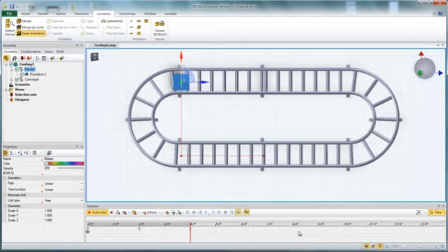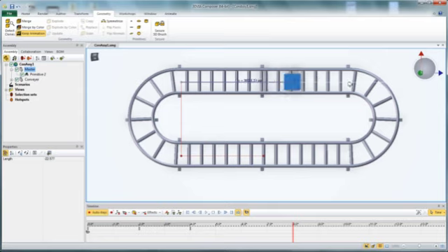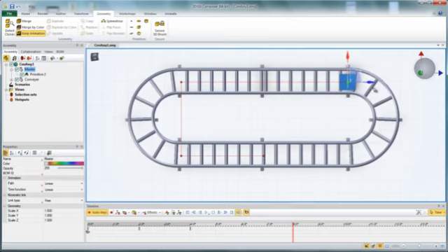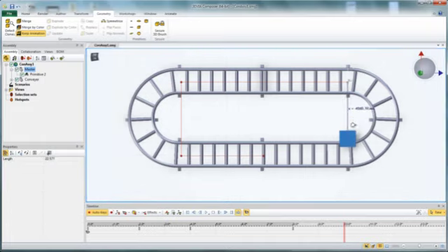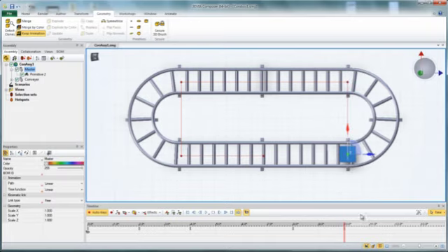And then we will add another 4 seconds, animate all the way down to this side, and then 2 seconds more, drag it right to here. Now I could drag this back on top at 12 seconds, but I want to copy this first key.